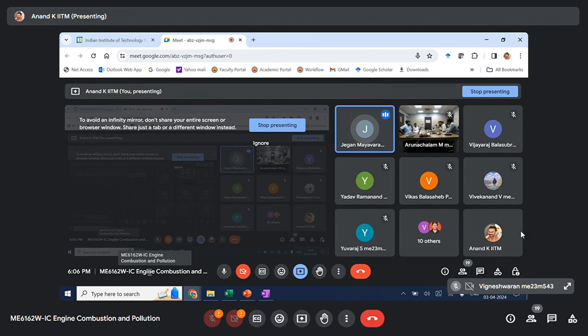That is why we have 0 to 180 degrees for one encoder and 45 to 225 for the second encoder. In addition, we have a pickup sensor near the flywheel side, as a supporting reference to not only depend on the forward of the engine, but also have the aft reference. So that's the reason we have this encoder offset between these two encoders, 0 and 45.